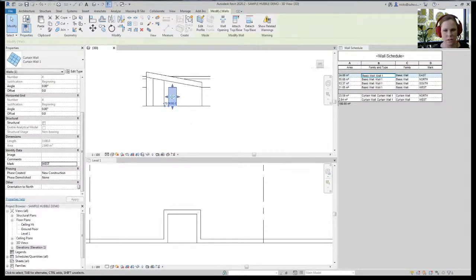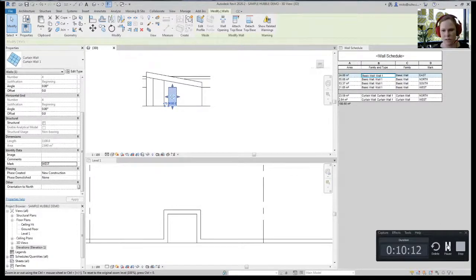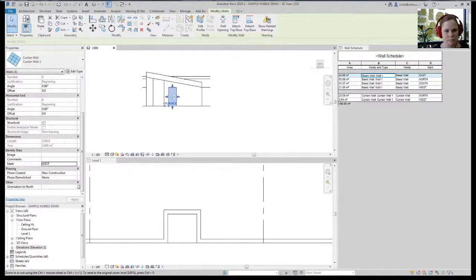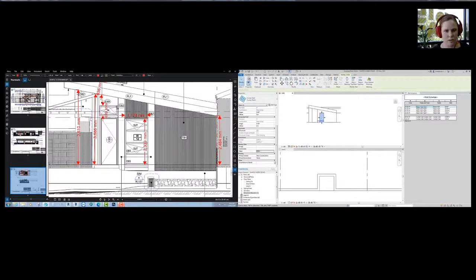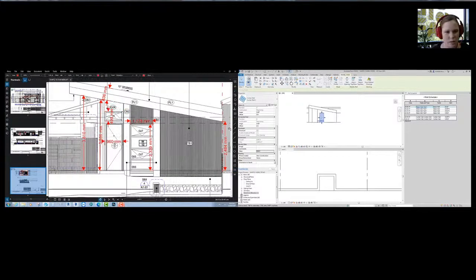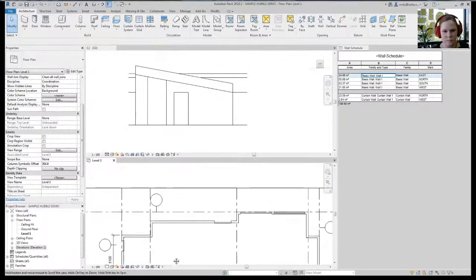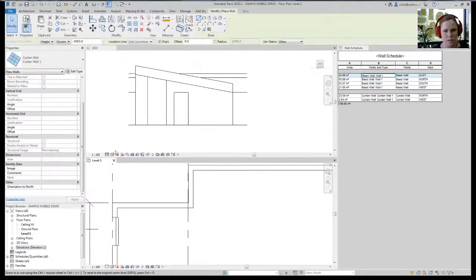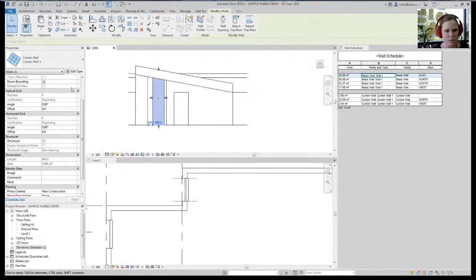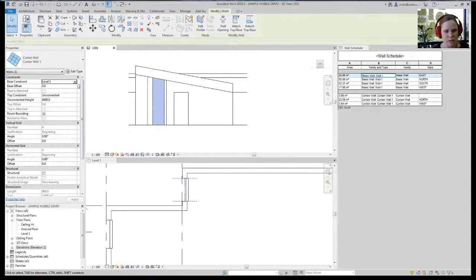That's good. Okay, let's see what other bits we need. Okay, so back in Bluebeam, just also got the high level window that's above the entry door, also west facing. In this instance I haven't actually put the front door in because in this particular project it's an airtight door, so I'm less concerned that that's going to affect the performance. If it is a regular door I would probably put it in, especially if it's glazed.